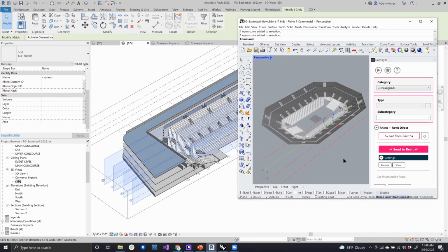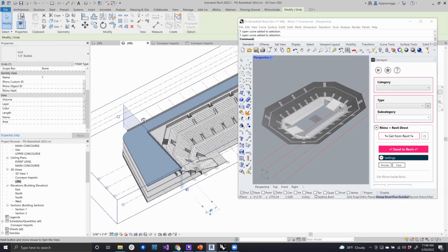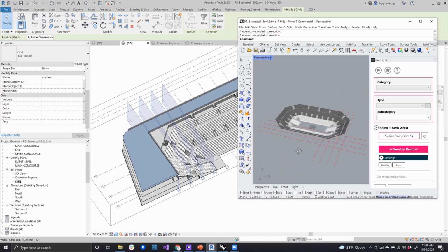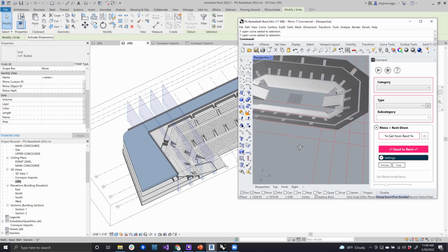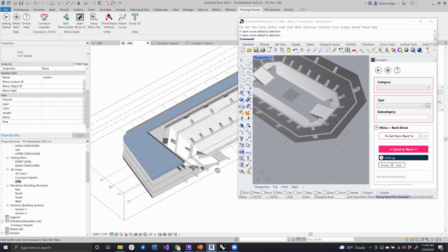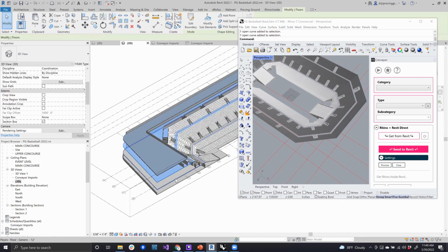So we now have these as a way to see where objects are lining up. If I wanted to continue, maybe design some columns or other components inside of the Rhino environment, or locate a particular set of Rhino geometry against these grid lines, this feature allows me to coordinate that back and find some of the key organizational datums to work with. We can also do the same with objects like floors and walls.